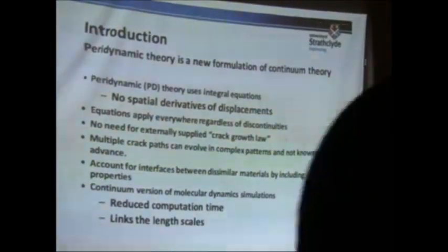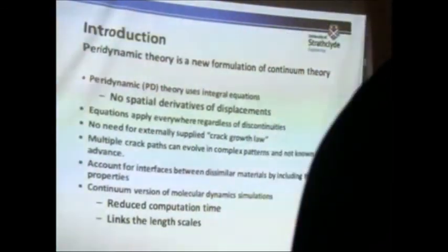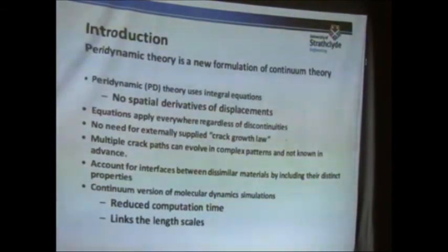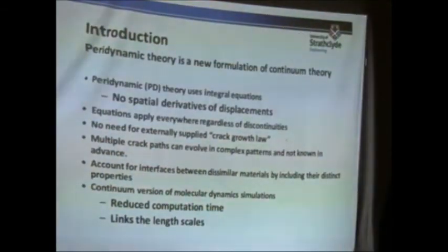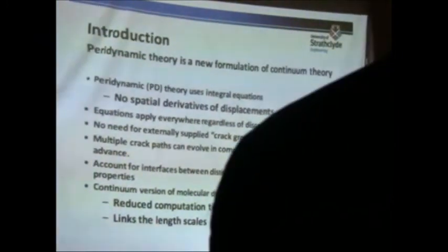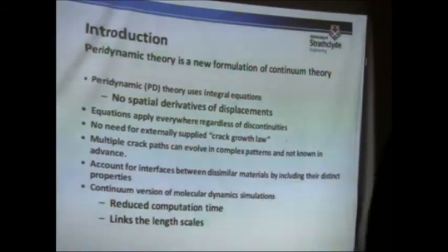Exactly. So when we talk about Cauchy's continuum formulation, which we now call classical continuum mechanics, that formulation uses partial differential equations. But in this formulation, we are using integral equations, and our equations don't have any derivatives. Not using derivatives in the formulation brings us several advantages, especially if you want to model fracture. Our equations are always working, so even if there is a fracture or not, they're always valid.